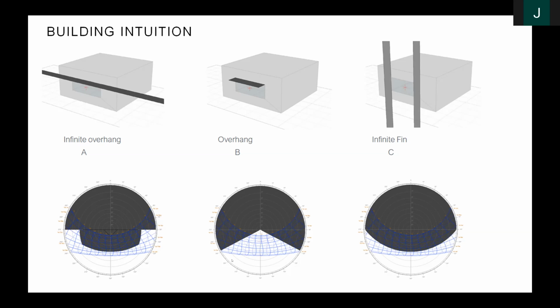And of course, this leaves as an infinite fin something that goes from at least as high up as the point of interest that you're interested in here, because the horizon needs to be blocked. And then it goes up all the way into the sky, up to the zenith. And that's what an infinite fin would look like. Of course, if the top ends somewhere, then this top portion of the pie slice is not blocked. So you would not want to shade that.